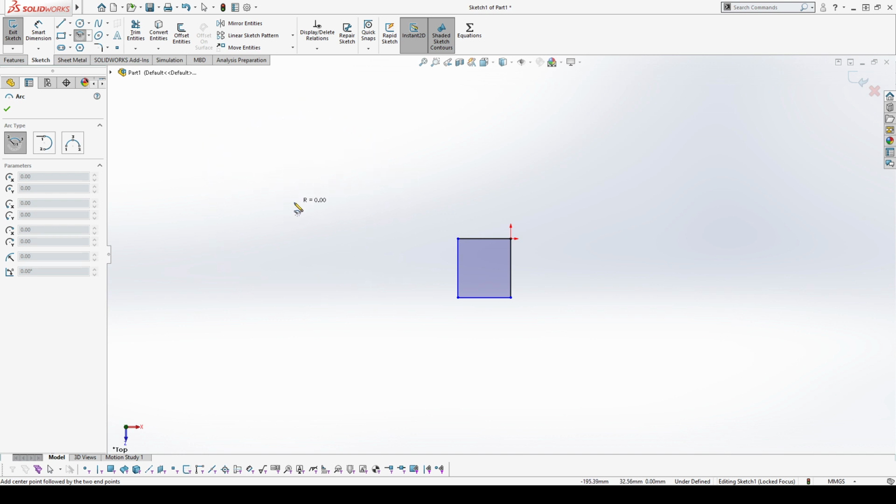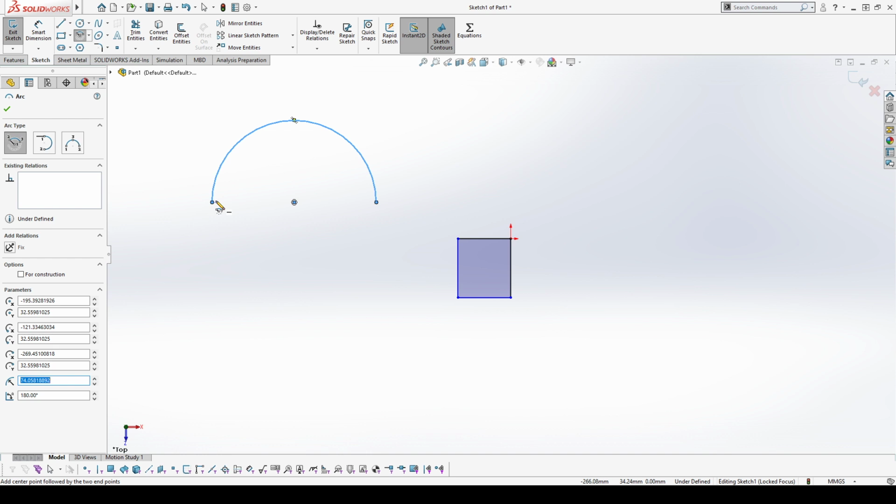For center point, we start with our first point, and we place another point, and then we start to draw our arc. And then if I want to draw the other way, I hover over that point where I started, and it lets me start drawing going around like that. And sometimes you have to hover over it a few times to get it to do exactly what you want. But yeah, so that's your options. That's one of the ways to define an arc, if you know your center point, draw your radius, and then you define your angle. The other way is to define your diameter first.